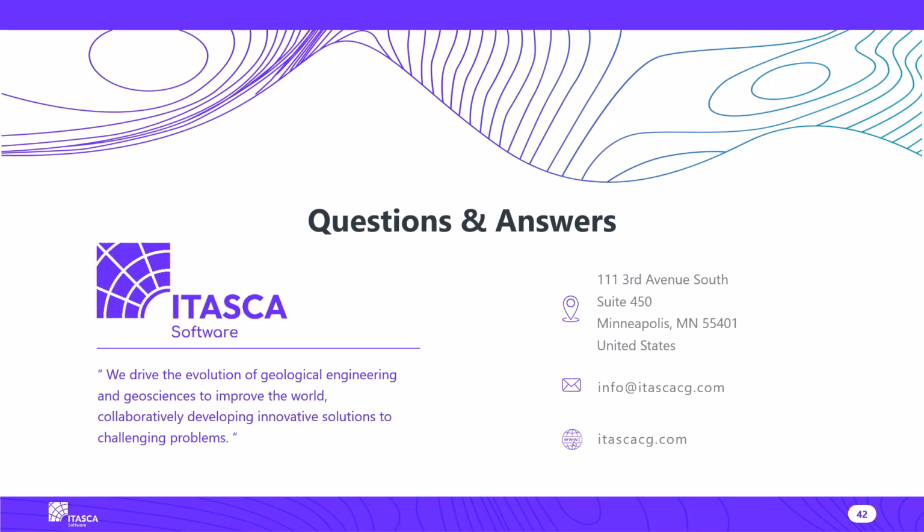Great, thank you. And I guess I would just add that since this project was conducted, ITASCA has added what we call zone joints to FLAC 3D. Zone joints are similar to the interfaces that Catalina was mentioning, but they behave more like 3DEC true joints with contact models. They are, I believe, faster, and they also work really well where we get many joints or faults intersecting, and behave better than we were finding with interfaces. So that's a new development in version 9.